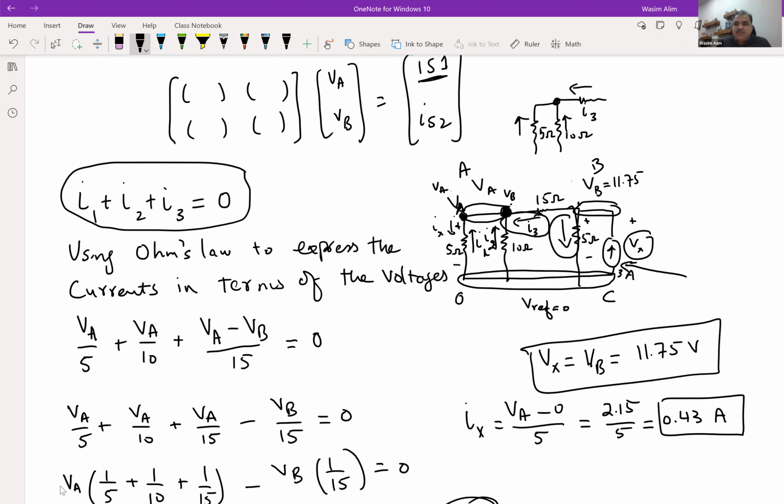So once you have drawn the arrows, you write the equation, then you write the currents in terms of voltages and resistances. You just apply, of course, Ohm's law. So I is equal to V over R. You write it in terms of V over R's, and you get a final equation which is in the most simplistic form, because it's easier to solve if you're going to be doing it by hand.